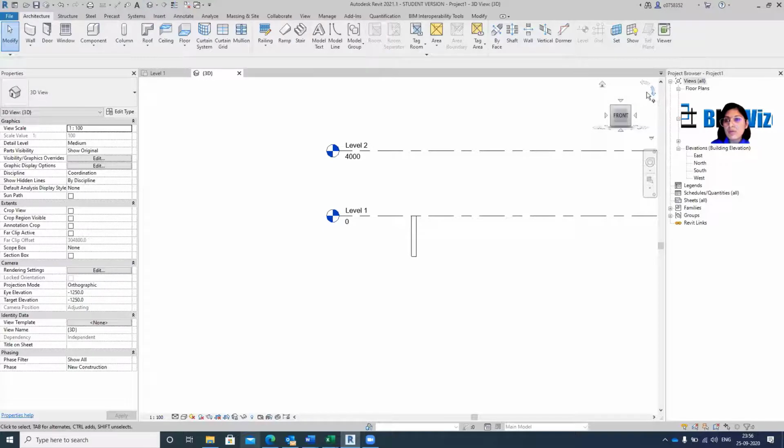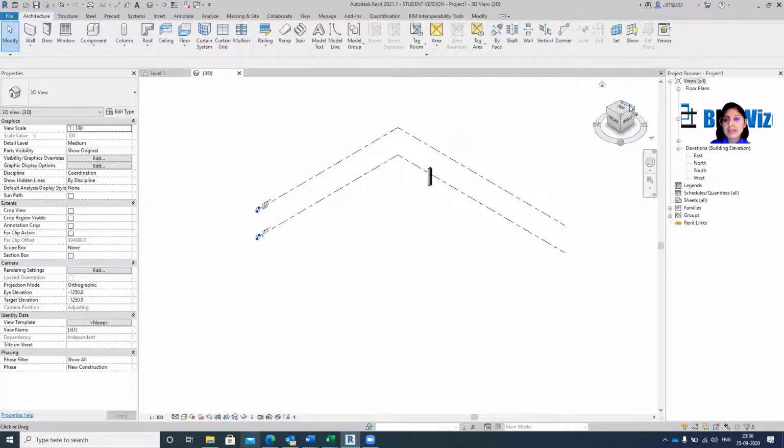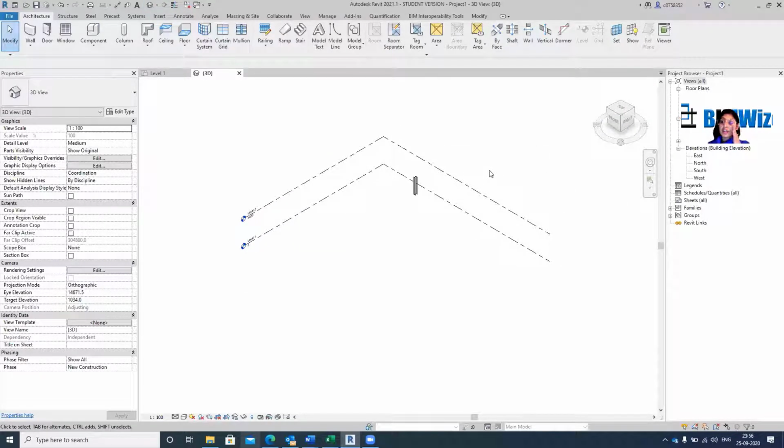that in 3D view. If it's visible in 3D view, that means it might not be at the right level, or not at the right location. Crop window is a good guess because sometimes your crop window is smaller and you've placed something outside the crop window and you've not seen it. And that's a good place to start.